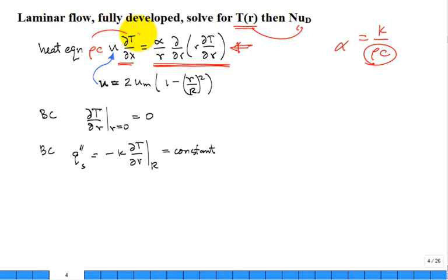You have the advection and diffusion. They're balanced. For my pipe flow, the advection is in the x direction. What about the direction for the heat diffusion? It's in the r direction. Remember, our temperature profile typically is hot at the wall and cold in the interior, so the diffusion would be in that direction, from the hot wall surface to the cold interior.